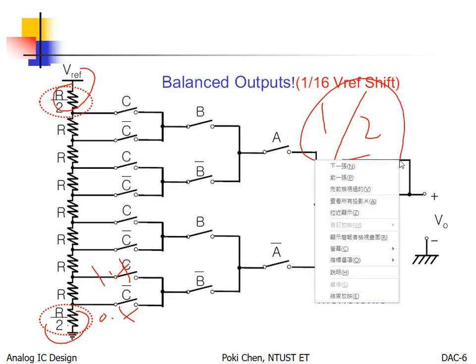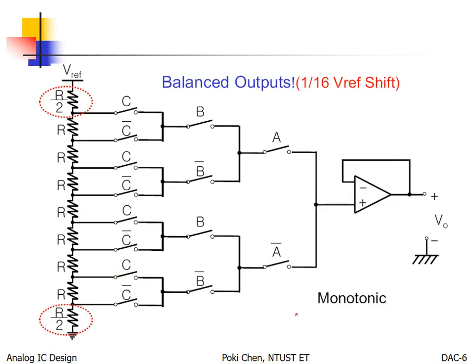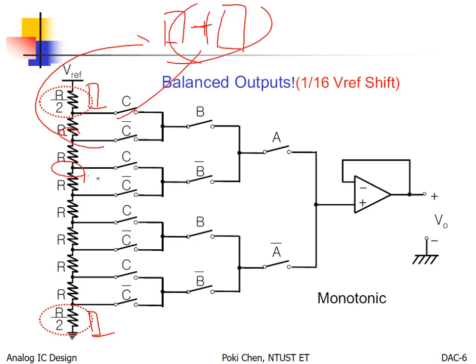Again, I need to warn you. Hey, look, I have a unit resistor. Then I cut the unit resistor to be this and that. No, ridiculous. On the contrary, the minimum requirement is I have a unit resistor here, a unit resistor there, and then 2 unit resistors connected in series with each other. And then again, you need to randomize. Not the first, the second. No. Forget about it. That is what you need to know.